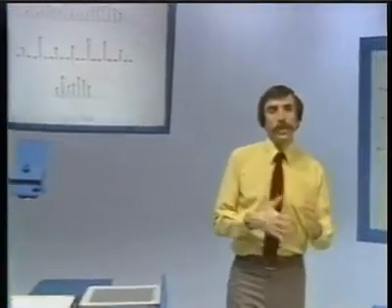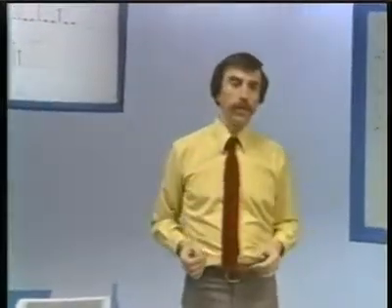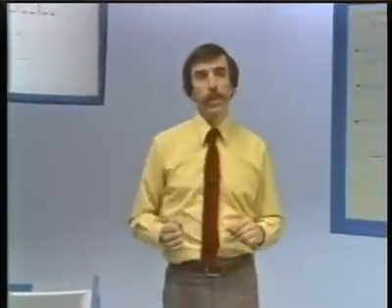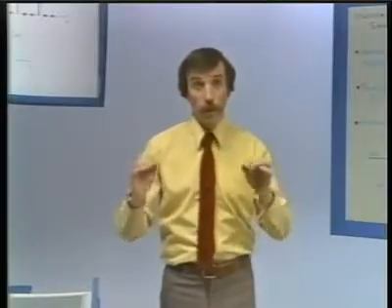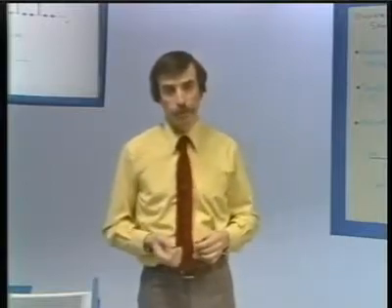Well, let's say, for example, that we want to carry out sampling, and what we're talking about is a sequence, and let's say the sequence is stored in a computer memory. As you can imagine, the notion of sampling it and actually replacing some of the values by 0 is somewhat inefficient. Namely, it doesn't make sense to think of storing in the memory a lot of zeros when in fact those are zeros that we can always put back in. We know exactly what the values are, and if we know what the sampling rate was in discrete time, then we would know when and how to put the zeros back in.